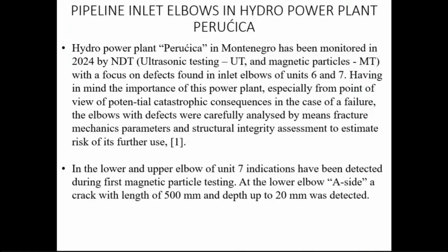So out of 42 up to 52 millimeters of thickness, almost half of the thickness is occupied by a defect. This is cast iron and a very rough one in a sense, a big one, not a precise casting, just classical casting. So this is why the thickness varies so much.